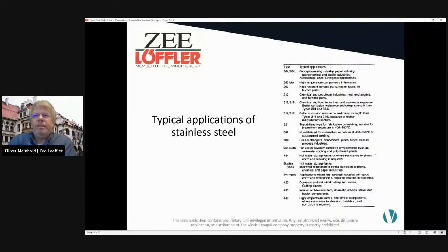Now looking at the table of typical stainless steels, if you look at the top right, you see 304, which is nowadays probably the most common stainless steel used to create all the equipment in the brewing industry, whether it's the piping, the brew house equipment, the fermenters, and so on. If you go back in the past, quite often you saw more 316s, which is a higher grade. It's a little bit better than 304, but of course, more expensive. And the difference is not that dramatic. If you have a good maintenance schedule for passivation and cleaning properly, I think you can have the same life expectancy out of 304 stainless steel equipment versus 316. Further down, the grades get very extreme, for high chloride levels or high temperatures. But 316 and 304 are specifically suited for our typical temperature range and the corrosiveness from cleaning and so on in our food and beverage industry.